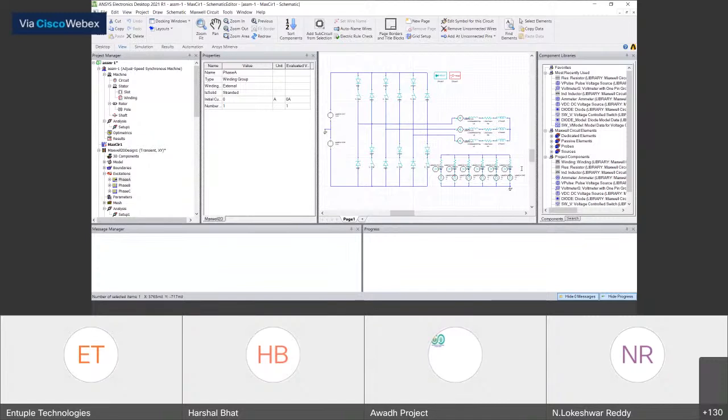Can we use it to analyze the battery of an electric vehicle, like how behavior will change? Those aspects are generally chemical changes, and battery modeling itself is normally done in Fluent, mostly in Fluent CFD, and some part of it in Simplorer. Maxwell is generally not used for that. But of course, if you have very big batteries with bus bars within them, then the current distributions there can be done in Maxwell. Any other queries?